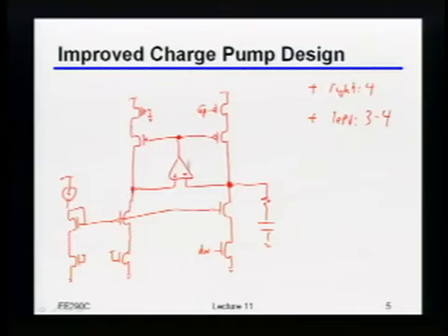Okay, and now, by the way, building this little op amp here is also a little bit fun because you have to be careful about the stability. And actually, because the range of voltage you want to tolerate here is pretty wide, you might need a wide input range on the op amp. But basically, this is really starting to look the way real PLLs are built. Okay. Make sense to everybody?